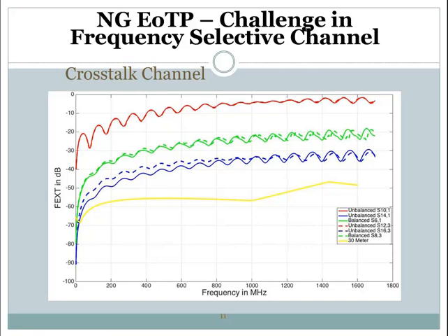It's obviously the strongest crosstalk we see in this figure. And the green curves in the middle, they are the balanced mode, so it's between the pairs of the 1 meter cable. It's not as strong as the wire-wise crosstalk, but it's still stronger than the 30 meter long cable. And the two blue curves, they are the crosstalk between the wires from different pairs in the unbalanced transmission. So this crosstalk is relatively weaker than the balanced mode.